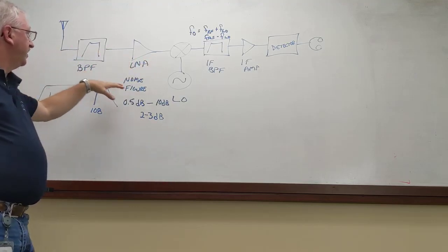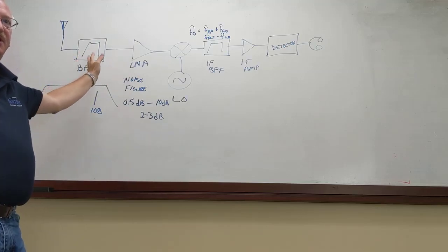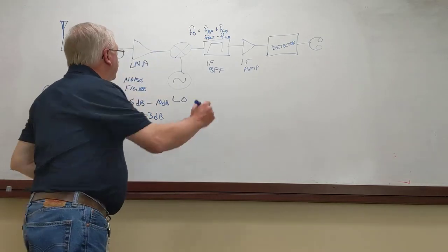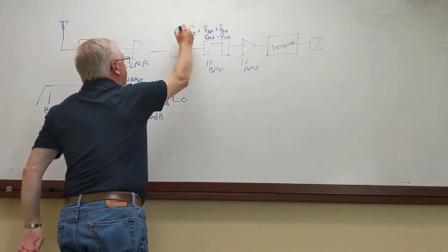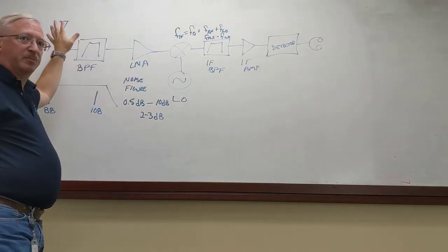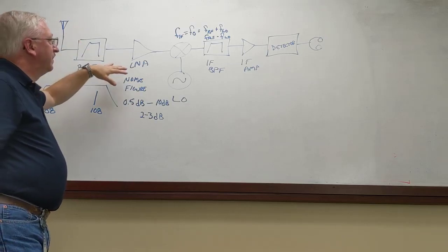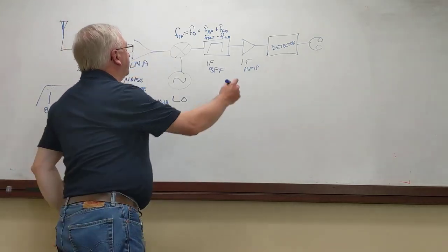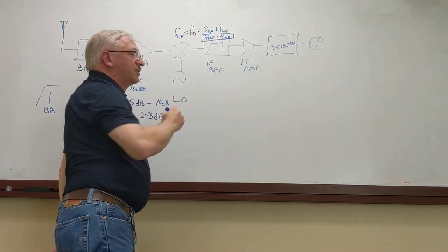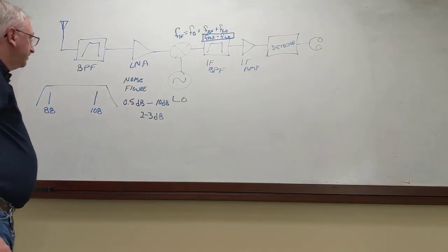And so typically, based on how you do your system design and how much tuning range you have, you pick your IF frequency, based on the parameters of what your LO tuning can be, what your input comes to be. Usually it's the subtraction most of the time in most of your applications.